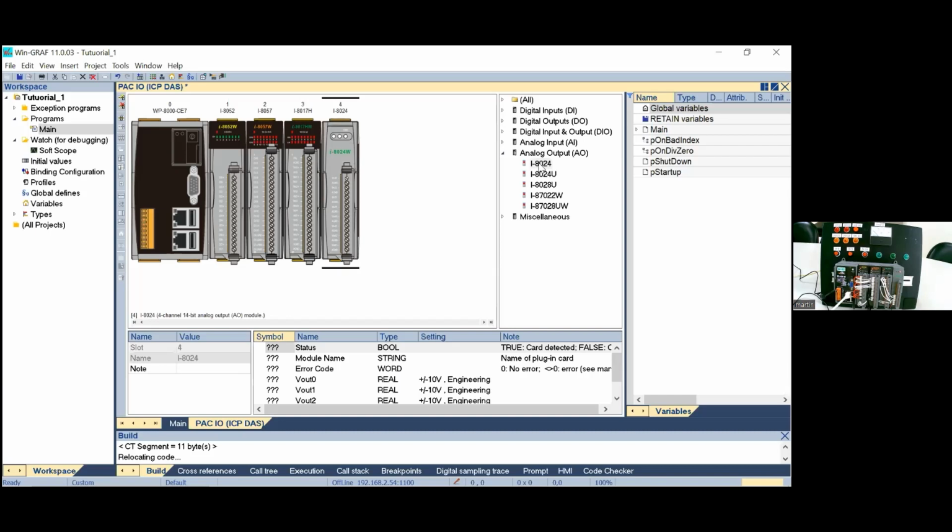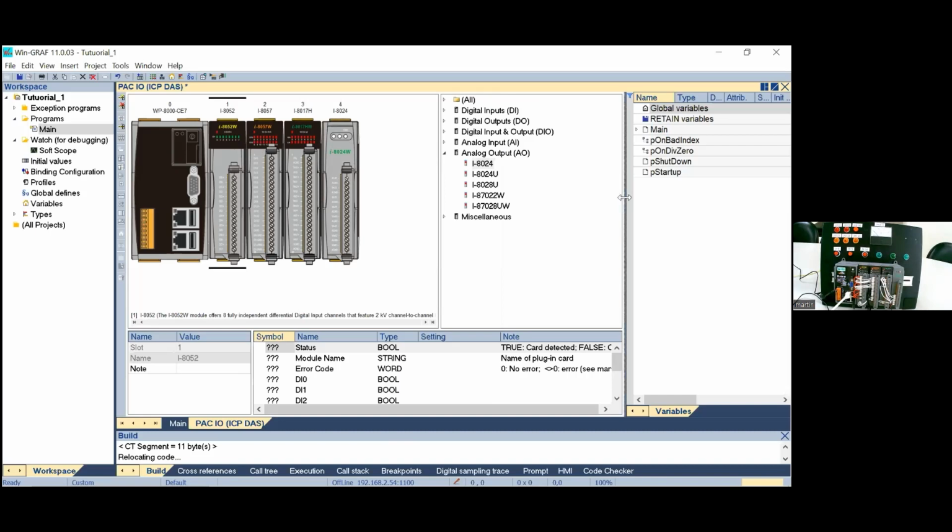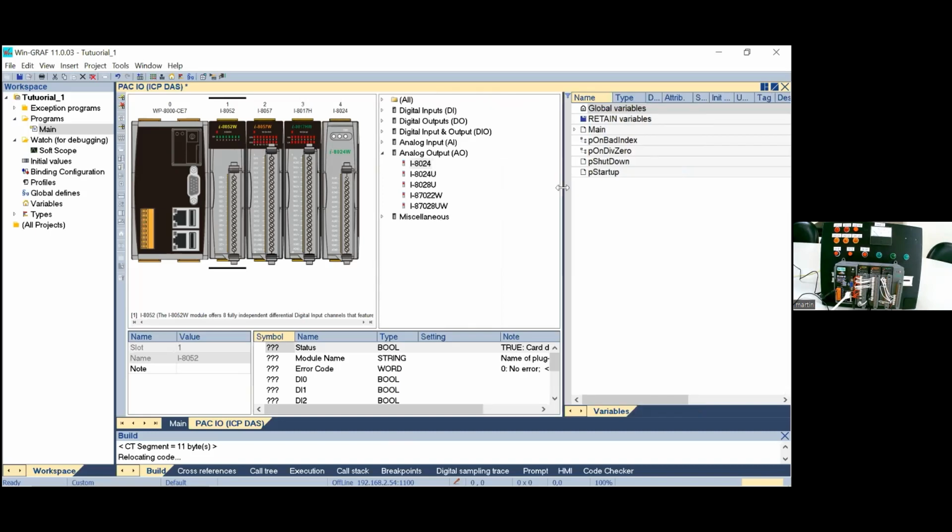So now it is necessary to create and assign for each physical channel a variable so that the PLC logic program can directly read the input status and control the output of each channel. For this, we will therefore for each module create an array and map each array element to the individual channel. We will define this array as global variables.